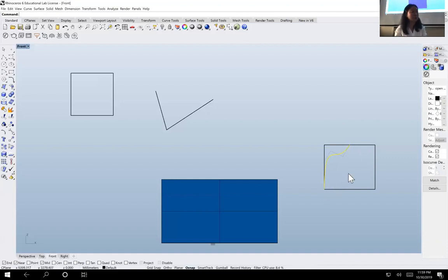You click and you select a point which is not on the curve. They're called the control points. They're not on the curve. They're here and there. They're off the curve. But if you drag, okay, now since I talk about it, the control point is the magic for Rhino. Without the control point, Rhino is like handicapped. It cannot even function, because that's where we control the surface and the line, all this fancy curvy stuff that goes with the control point.